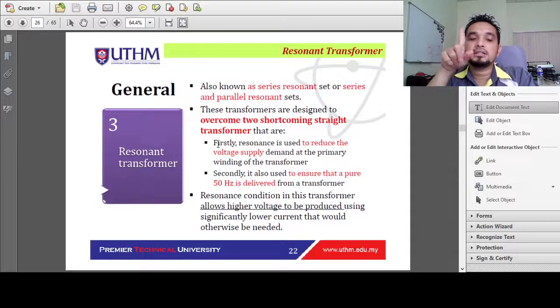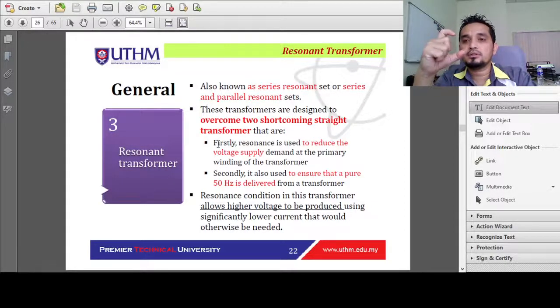First, as I mentioned, the resonance will amplify the magnitude. So we will use this in case we really need to generate a high voltage level and we don't have enough cascaded transformers. We will use the resonant transformer concept to generate a much higher voltage level, because resonance amplifies the voltage and amplifies the current. So we manipulate the problem to become a solution.